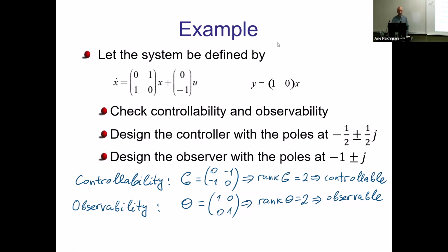Okay. So for that system, C matrix is 1, 0, D matrix is 0. You want to check controllability and observability of the system first to make sure that you actually can design controller and observer. So pay attention that you can design the observer in that case if the system is observable. Okay, we discussed it in one of the previous lectures, but this is a condition.